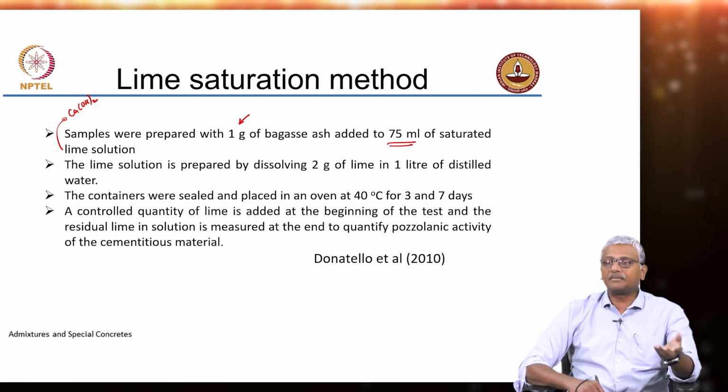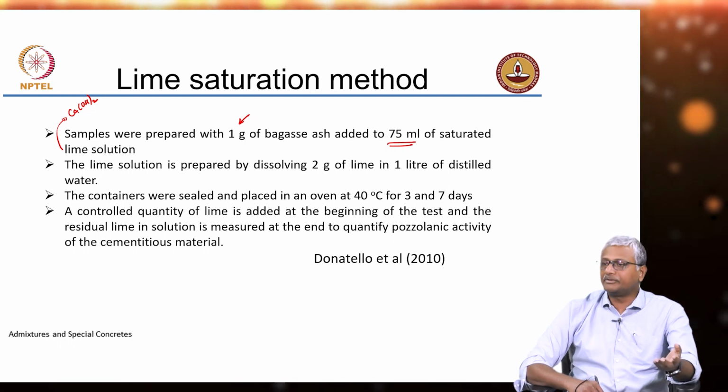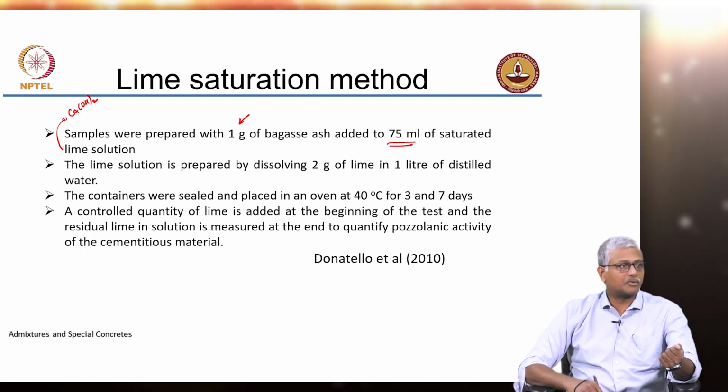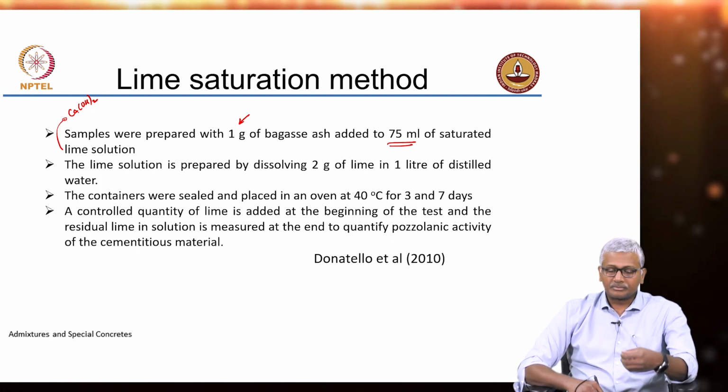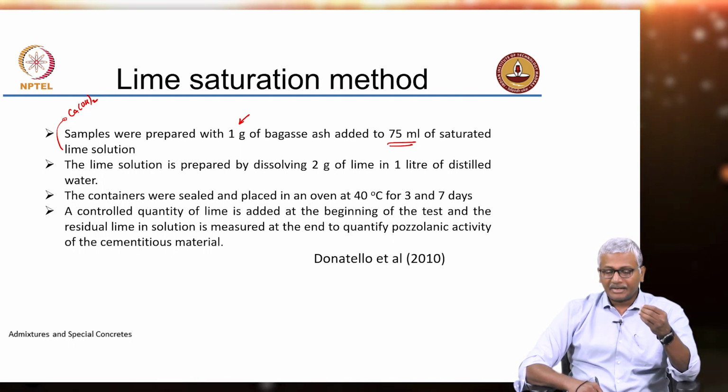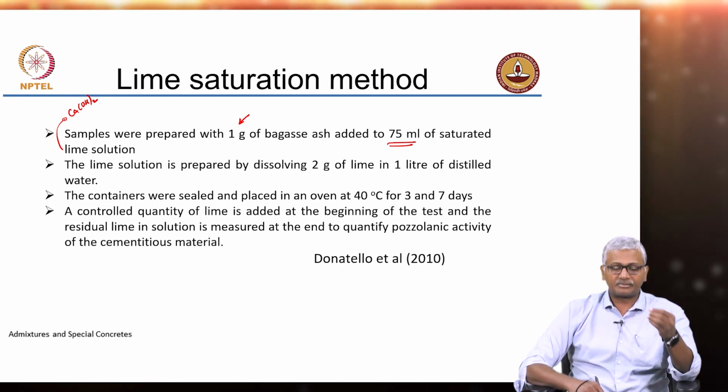What is going to happen with time? If the pozzolanic reaction happens, the lime content will reduce, the lime content has to reduce. Okay. So, what we essentially do is the residual lime in the solution is measured at the end to quantify pozzolanic activity of the cementitious material.